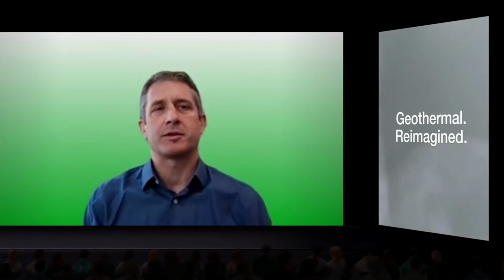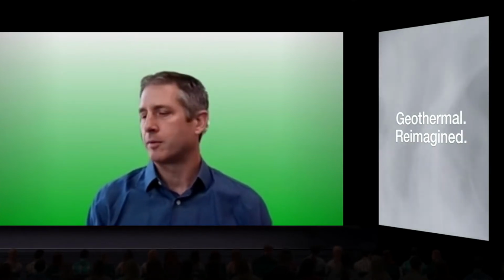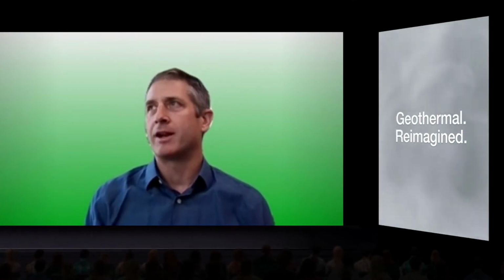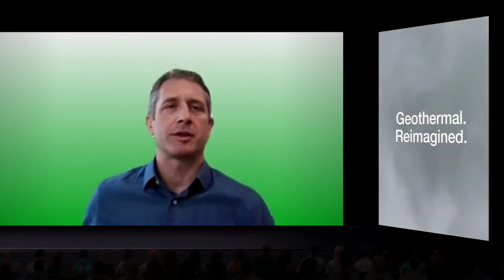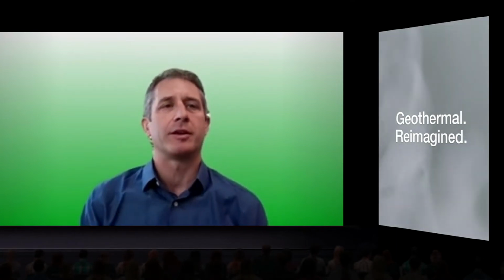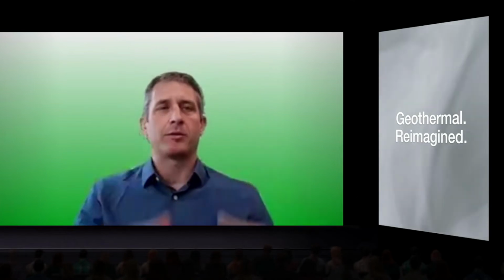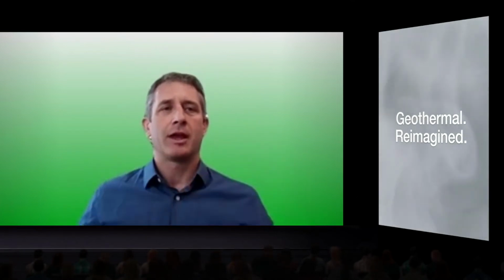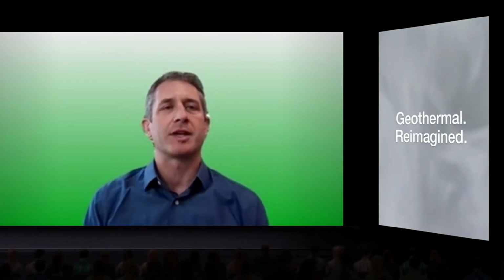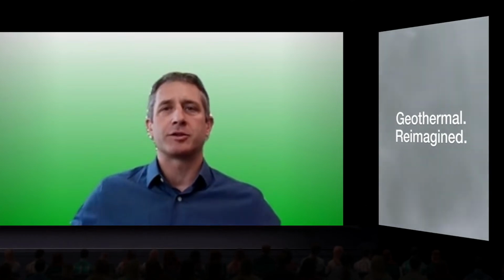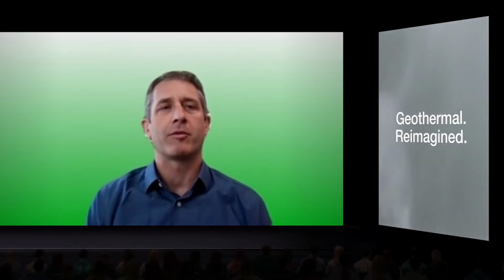I think it's a good question. It is something that we're involved with, especially with DOE and NREL research. You're right, it hasn't changed very much. I think someone touched on the multilateral, and we have done some drilling where you drill a surface location and have 2 or 3 legs from the same. For us, we've done that typically on the injection side. So we're trying to distribute the injection to reduce cooling, and also increase the total flow that the well will take. So for us, that was a bit of a step forward.